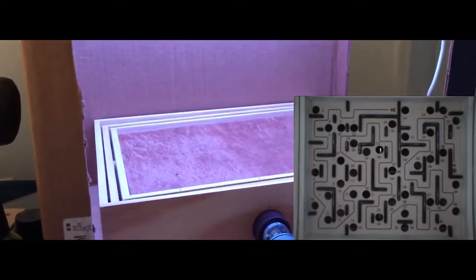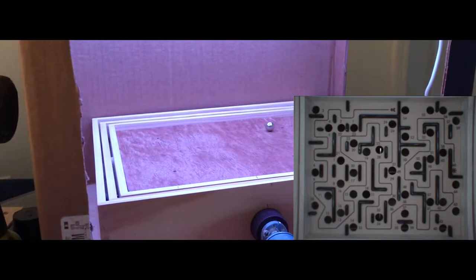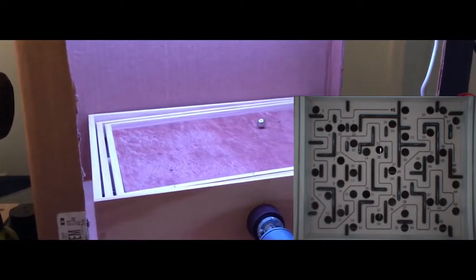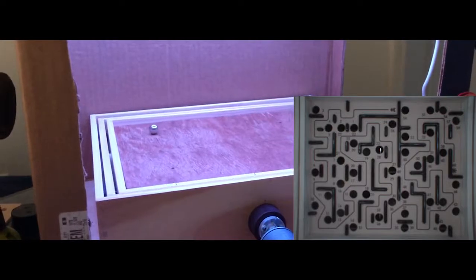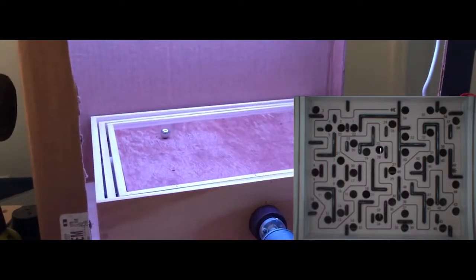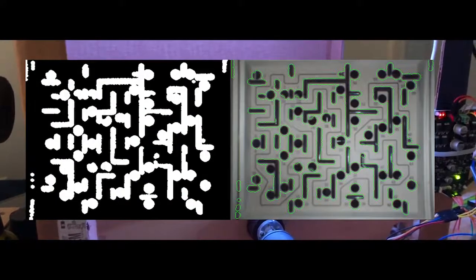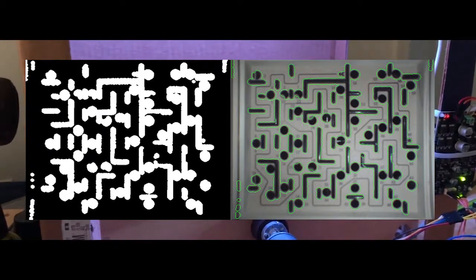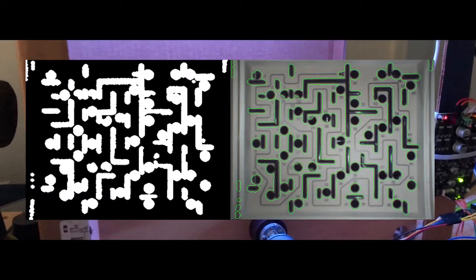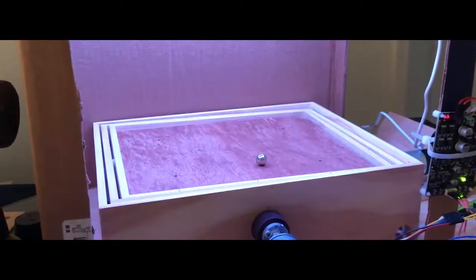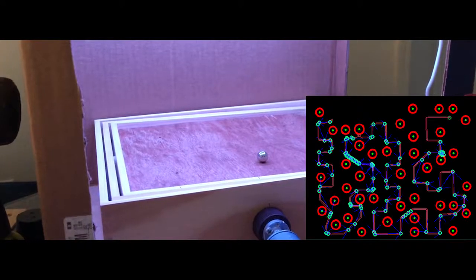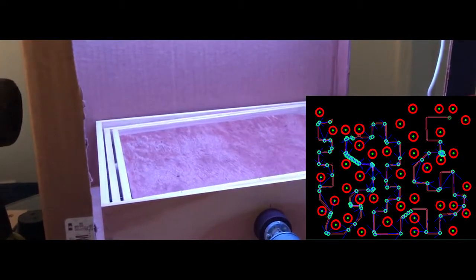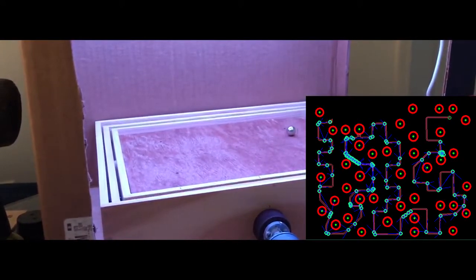To mark obstacles on the board, such as walls and holes, we initially take a capture of the board from above, and with this one image we convert it from red, green, blue to hue saturation value, and use contouring to find where the walls and holes are. After this, we then use Canny edge detection to follow the guiding line from the beginning of the course to the end. With this path now laid out, we can place nodes along it, and then vectors are placed in between the nodes. This creates a path that we should generally follow to get through the maze.